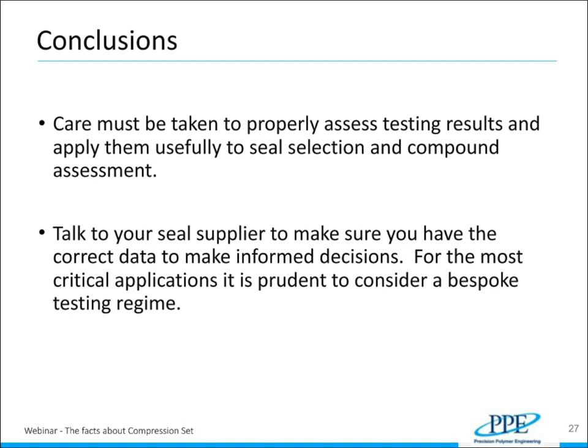So like we said, care must be taken to properly assess the testing results, and really make sure we've got a full picture before selecting our seals and assessing our compounds. And I suppose the point we'd say here was talk to your seal supplier to make sure that you really have all the data required to make these type of seal selection and compound selection decisions.